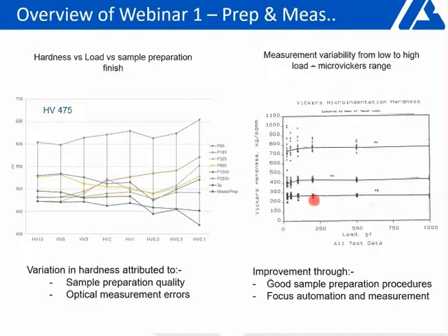So for the low Vickers levels, you get good correlation, but you also see when you're doing low force, say 50 grams, 25 grams, there's a little bit of dispersion. This is more highly magnified when you're looking at the 700 Vickers level, and you can see the bell-shaped dispersion is quite high.